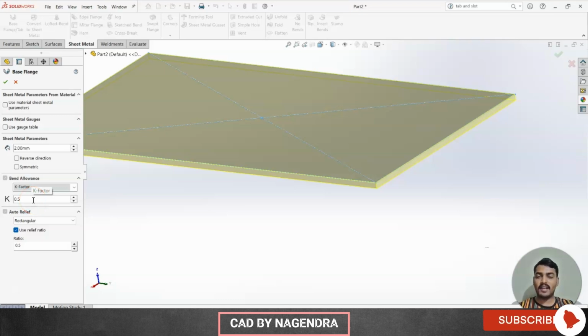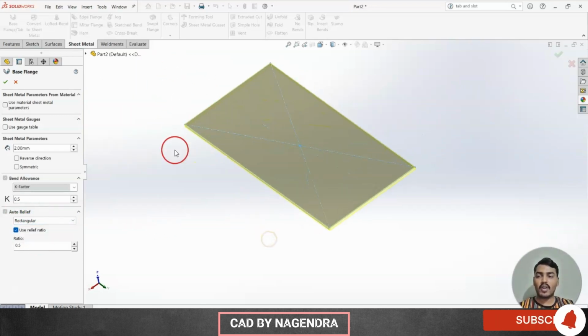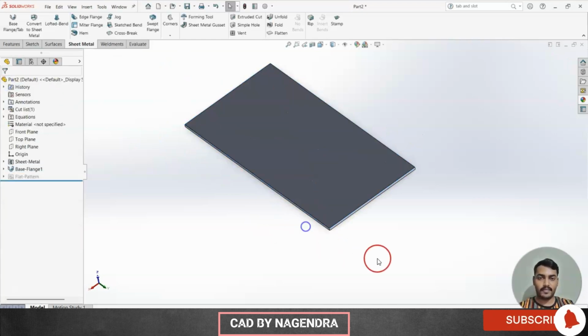Again, the formula and all we have already discussed in our basic sheet metal design tutorial. If you have missed it, please watch it. Then along with K factor, we can create a sheet metal part by using bend table or bend allowance or bend deduction or bend calculation. So in most conditions we will use K factor. So I am just going with K factor value. Then auto relief will be there. Different types will be there. About this I'll explain in one more option. So I will say okay.